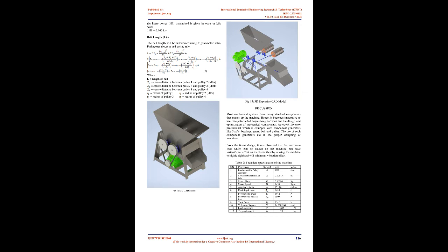The grating barrel diameter is 182 mm and the length is 300 mm. And the structural frame was made with 60 x 60 x 5 mm thick angle iron of top length 528.493 mm, base length 738.148 mm, slant length 619.565 mm, width of 450 mm and height of 624.428 mm.